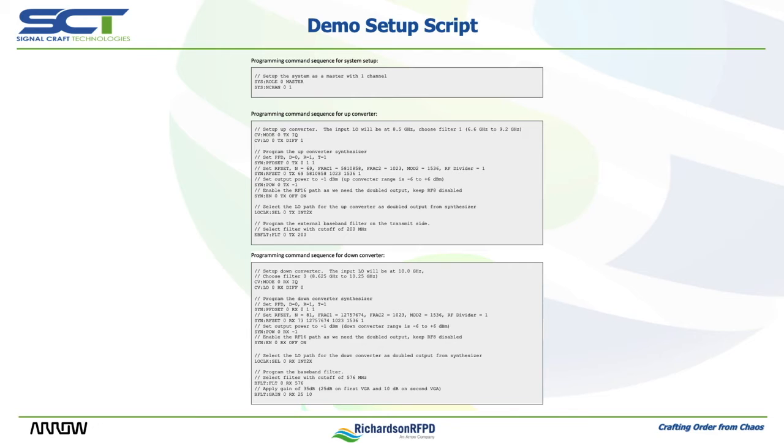The first line of the upconverter configuration script above sets the mixer to use the IF input. This is accomplished using the CV mode macro, followed by a minimal set of arguments. The first is the number 0, which targets the converter at address 0. You may remember that our platform supports the use of several converters cascaded together and controlled as a single unit.